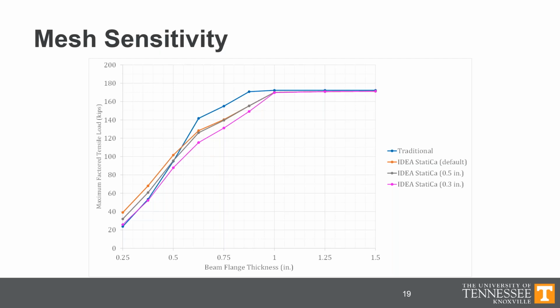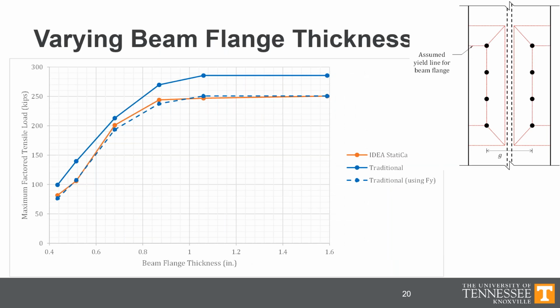for particular cases. In addition to bending of the T-Stub flange, we have bending of the beam flange. So in this case, the yielding pattern is more complicated. I show it up in the upper right-hand corner. The traditional calculations here are starting to get more complicated.